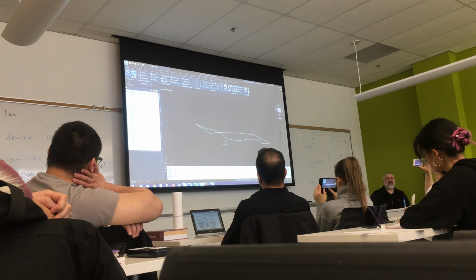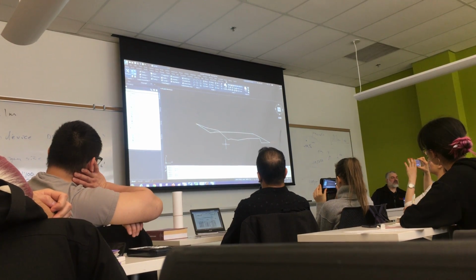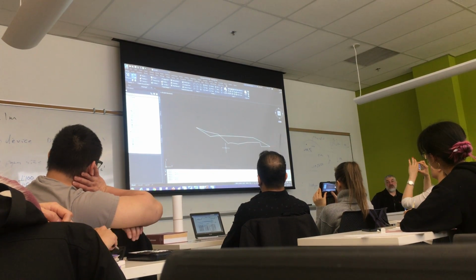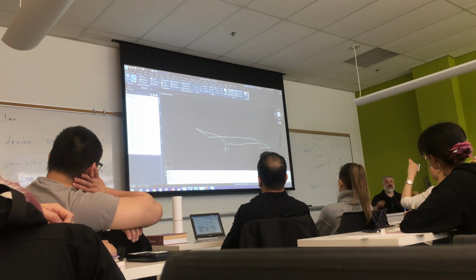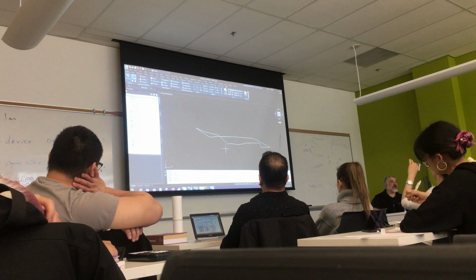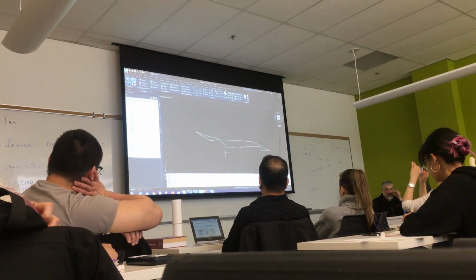Everybody see that? The boundary command is a very basic AutoCAD command. I don't think you learned that in DEA 001. And even if they had, it might not have made any sense to you until you see a reason for using it, which is what I've shown you right there. Because the boundary command is pretty powerful. If you want to trace it with a polyline, go right ahead. But it wouldn't be as efficient.